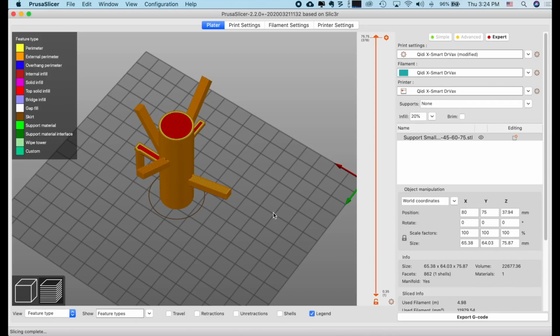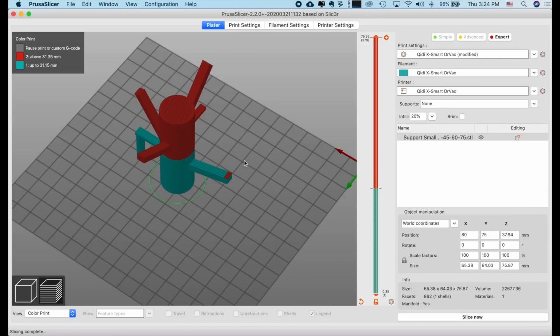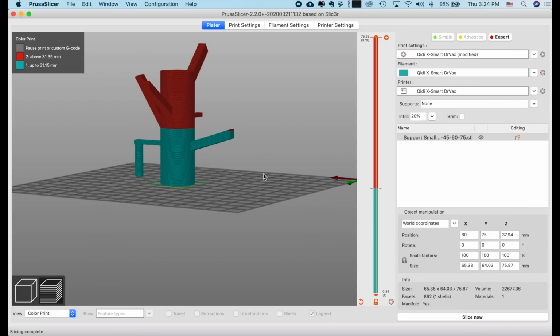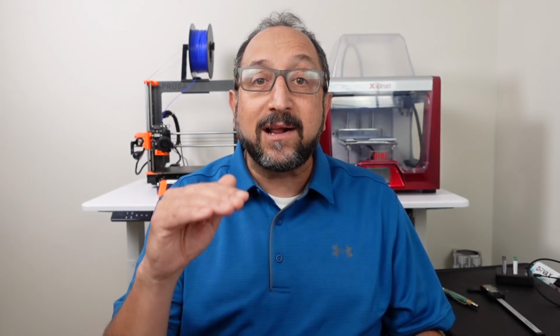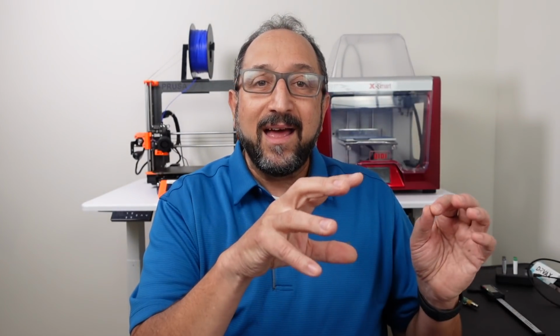One of the things that's nicest about the PrusaSlicer is that if I take this top arrow here and slide it down, I can go to a particular layer and then click on this plus key. And what I've defined now is I've divided my model into multiple colors. At the point where I have that split, the PrusaSlicer will insert an M600 command into my output, a G-code command, that will, if your printer firmware supports it, not all printers do, automatically pause your printer and give you instructions on the front panel about how to change the filament.